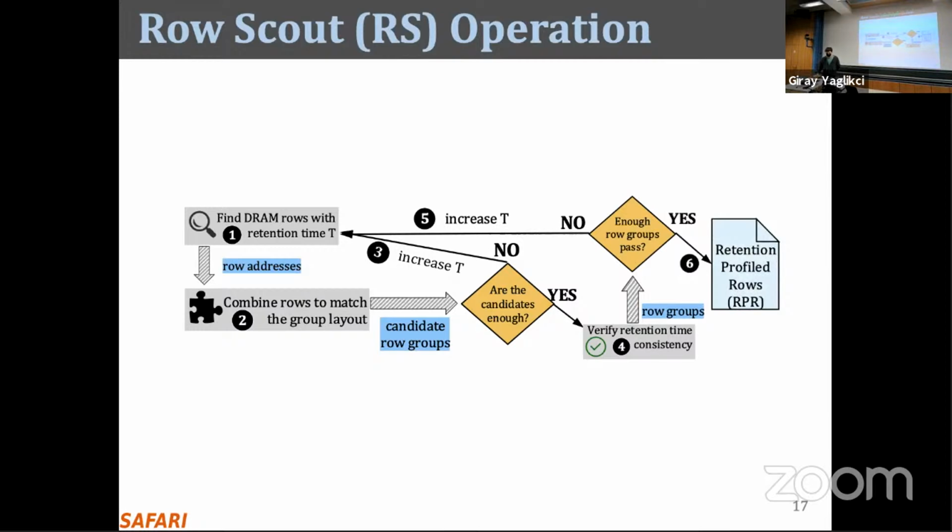Yeah, so let's say you measure the retention time of a certain row, let's say the row at address 100 of bank 0, right? So you find that it can retain its data correctly for 100 milliseconds. You repeat the exact same experiment again. Nothing changed in your experimental setup. But this time you find that it retains data for longer, for 200 milliseconds.